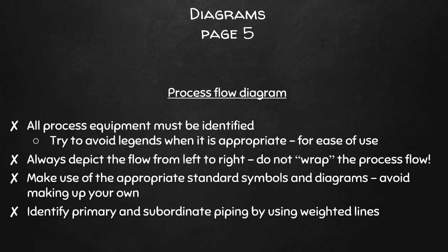Moving on, process flow diagrams. They must specify all the process equipment. And again, try to avoid legends in your final year. You can have them, but also just remember, we have 10 minutes that we sit with you in your design review, and you need to convince us that you've done the best design compared to your peers. It really helps to make your design readable. So when I see the reactor, I want to know this is the polyvinyl fluoride reactor.